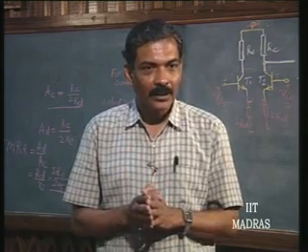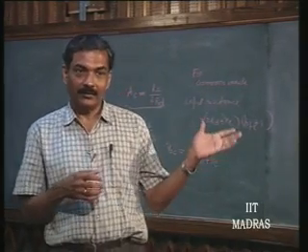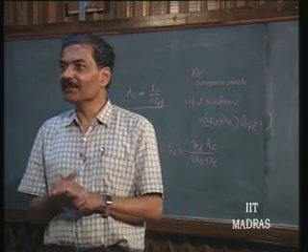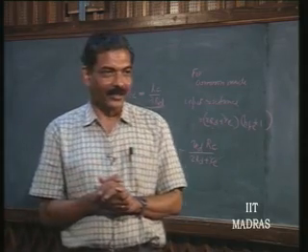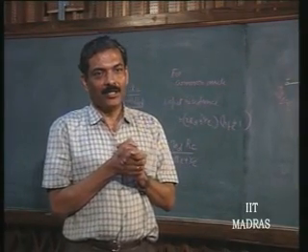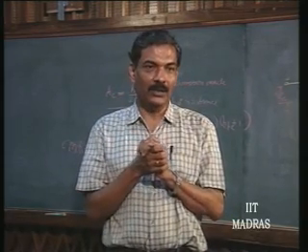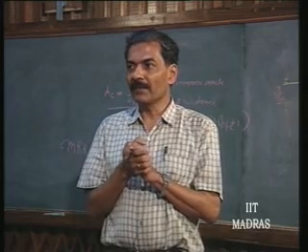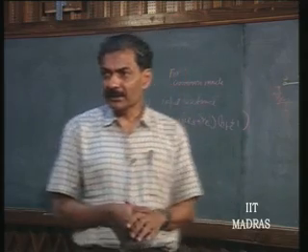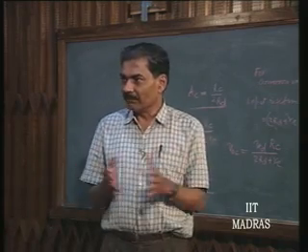The same thing is applicable when the differential amplifier is MOS based or JFET based, except that the relationship is not hyperbolic, it is square law, if you use a resistive load. But again, if you use a MOSFET itself as the load, then it becomes actually linear over a certain range. So, I would like you to do the same kind of analysis for the MOSFET differential amplifier using resistance as the load, and see what kind of relationship occurs between output V naught D and input VID. Rest of the discussions regarding the common mode rejection ratio etc. remain the same.